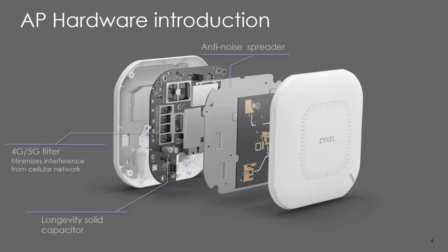The reason for this is we're dealing with solid state equipment here, and one of the leading causes of failure over time on solid state components is heat fatigue. The buildup of heat in there can over time cause the little switches that are part of the IC chips to fail. You can also put strain on solder joints. So by designing things this way, we draw the heat off the PCBA and off those components and help vent them out the back.